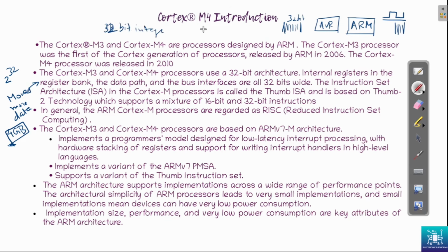for example you declare unsigned int some value in C, if you declare the same value on an 8-bit controller, the 8-bit controller having an 8-bit data bus has to break up that particular data into multiple bytes. So if it's a 32-bit value, it has to break it up into multiple bytes, and say you are doing a multiplication operation between two 32-bit numbers on an 8-bit controller. The code size is larger because it has to write a lot of assembly code to make that happen.